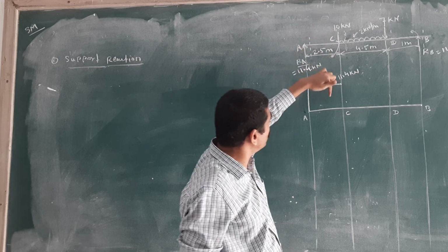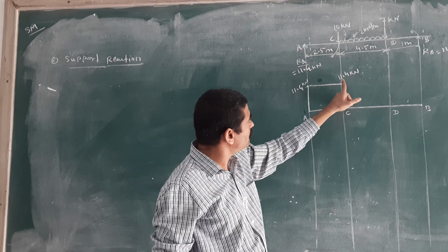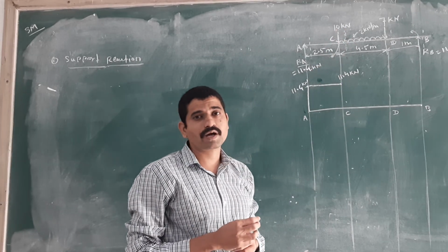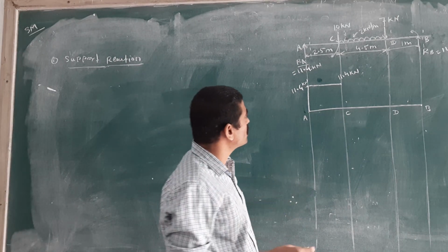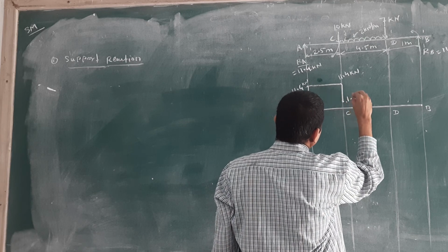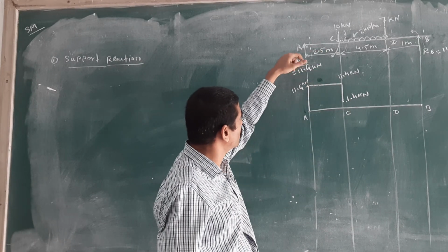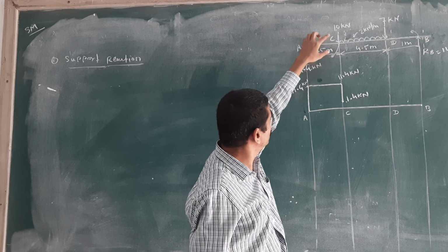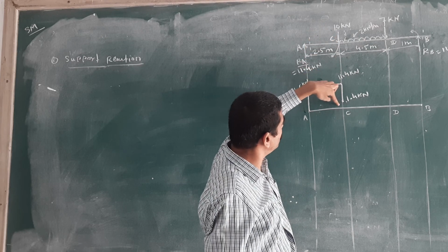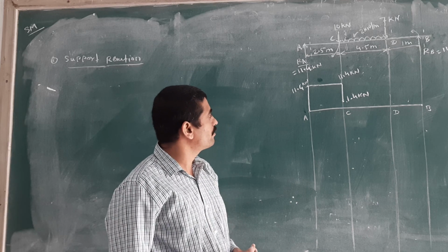Okay, then check how much load is at the C point. In which direction? Downward direction. Downward means negative. The negative force is 10 kilonewton. We have the positive 11.4 kilonewton and minus 10 kilonewton. Then how much will we get? Positive 1.4 kilonewton. Let's see here, suppose 1.4 kilonewton. Yes, are all of you getting it? See how to draw this. You only have to do this calculation: 11.4 kilonewton positive load, minus this 10 kilonewton, we get 1.4 kilonewton positive load. Okay, on the same point, C point.